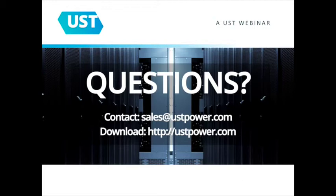Is the unit in series with the incoming power? Is there a bypass? And is this automatic? And that's from John. Well, the EVR would be in series, and there's an automatic bypass if something would happen to the EVR, it's automatically bypassed. That configuration would actually put you in a similar situation as the echo mode for the UPS.